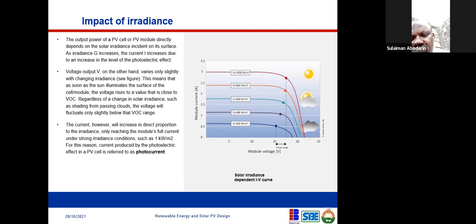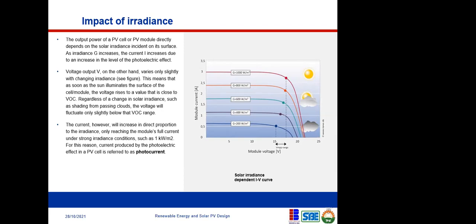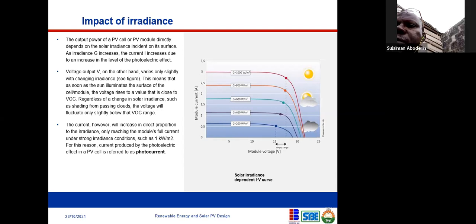Please, the cell arrangement, I think that is from the manufacturer. Yes, you buy the modules. That is left for the manufacturer. So as a project developer, please just look at the nameplate voltage, then you know how you combine the modules. But if you're talking about the cell level, that's left for the manufacturers. Okay.